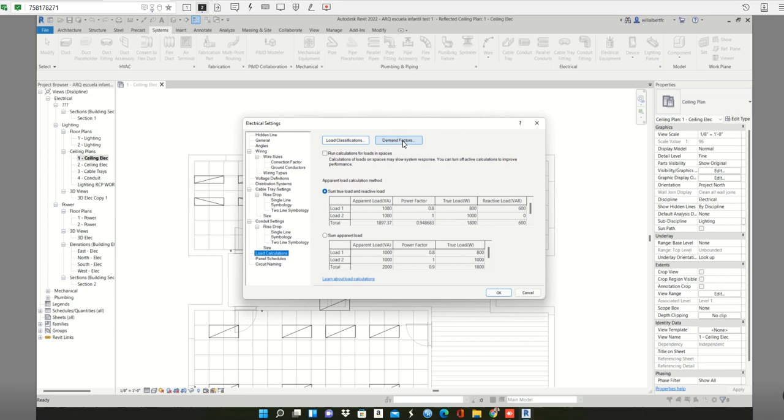For example, in the load calculation, you have to follow the code. You have to estimate the value for washer and dryer, electrical cooking, electrical kitchen, all of that. That depends on a lot of things. For example, if you live in Miami, you're not going to use a lot of heat devices like you would in New York.